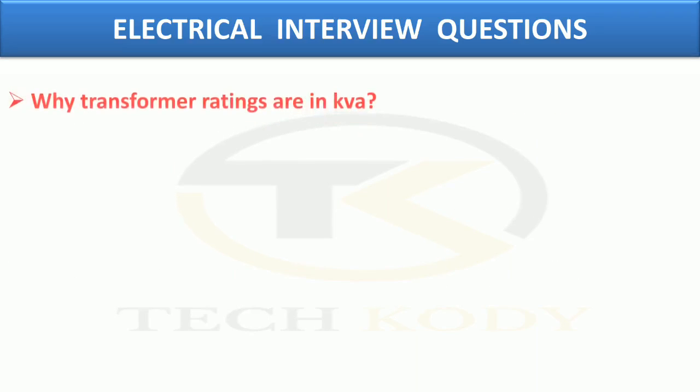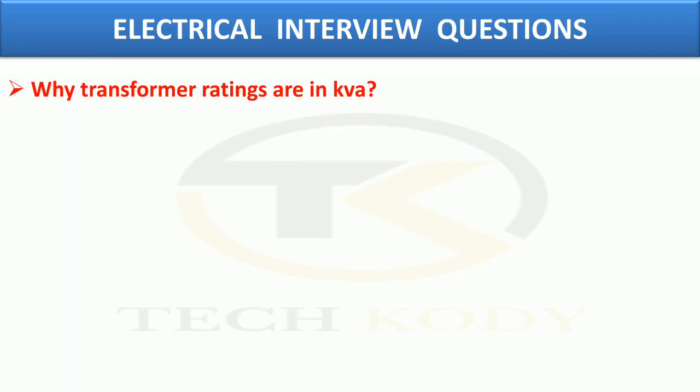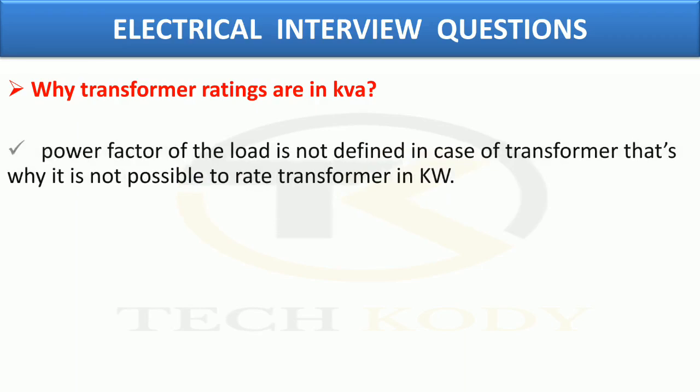The next question, why are transformers rated in kVA? The power factor of the load is not defined in case of transformers. That's why it is not possible to rate transformers in kilowatts.